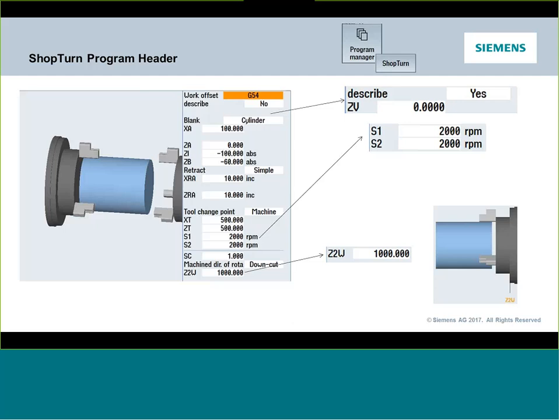And this is the retract location for the sub spindle or counter spindle prior to anything occurring. So first thing, start of the program, where do I want to send that sub spindle? So if it's staged anywhere else, it's going to move out, in this case, to 1,000 millimeters, which was the position that I decided to have my safe retract location.